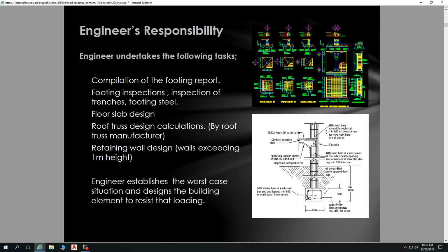Now that involved augering large piers, tying sections of the new retaining wall back into those piers. It was basically to save a house that was sitting up in an elevated position above another house. So it was a very difficult site to work in, but huge amounts of money can go into these things. Hence, you don't want to go designing retaining walls that are above that metre unless you know how those retaining walls should be designed and how things work in regards to soil loads, angle of repose, and moisture behind them, etc.